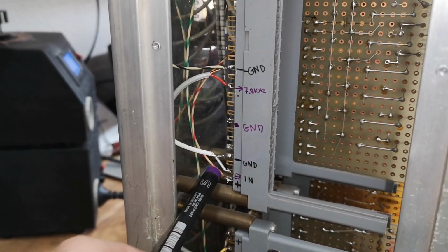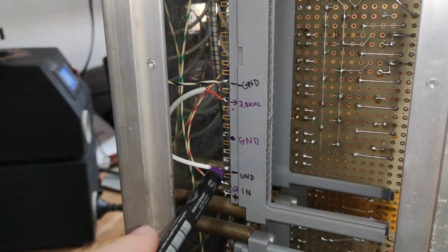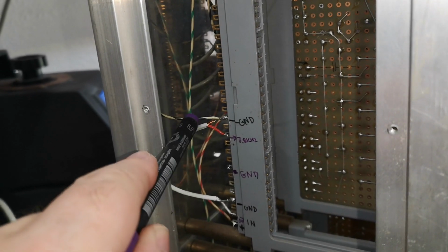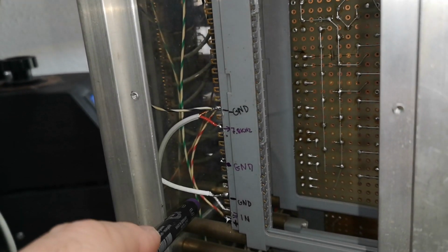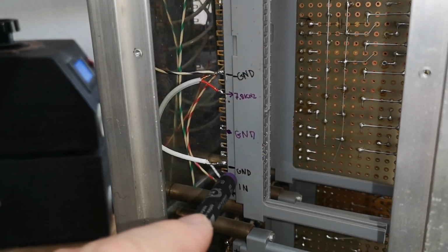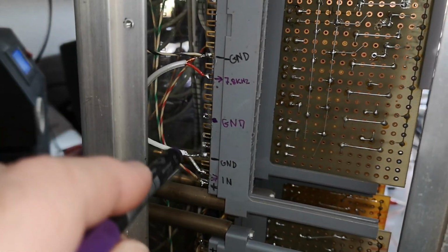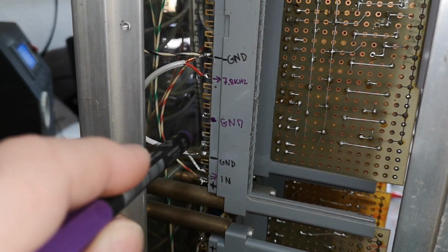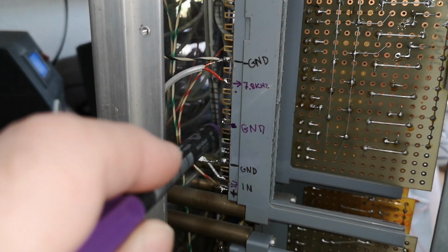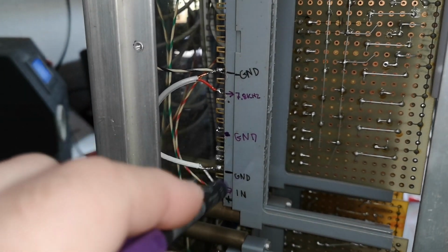So now we are a little bit later in the process. I've modified a little bit. I've connected ground correctly. I've added ground on the shielded cables on important signals. So there is a ground path or a return path to each of the important signals. Also, I've removed the capacitor and the resistor on the power supply, where they have added it right here, and then they used separate wires for grounding and stuff for that module.